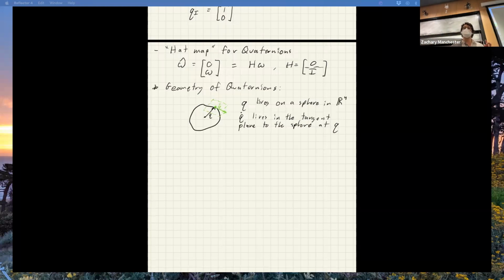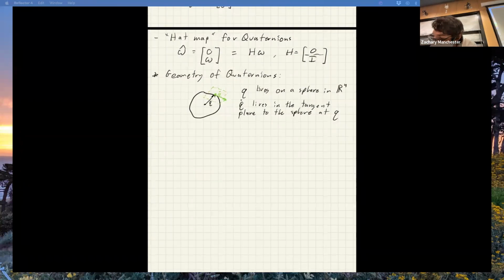And this is why we talked about how you want to write your pose as this quaternion that's 4D with this constraint because it doesn't have singularities, but then the rest of your dynamics, when you start taking derivatives and you write down angular velocities and then accelerations and all that stuff, all lives in this tangent space and should be 3D. Does that make sense? So the whole game here is we want to keep the pose stuff 4D, but then all the dynamic stuff that are higher derivatives should all be 3D, like we're used to basically.